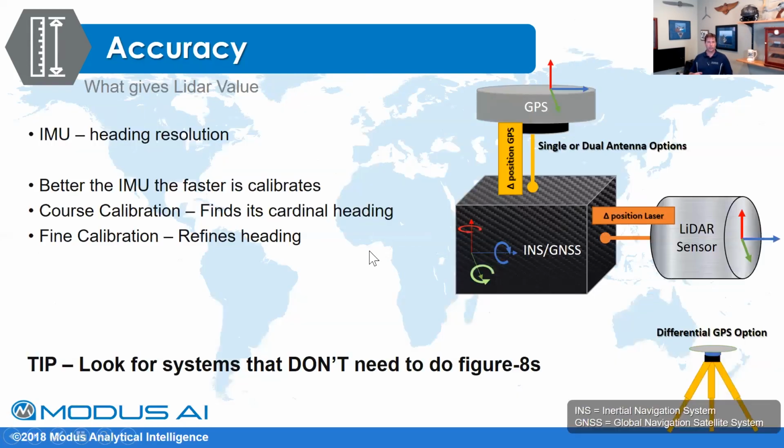All right. So the last little bit with accuracy is getting into the real system now that you know why that's important, and that has to do with the IMU. The GPS part of that is pretty germane. Some systems have dual, which does a little bit of heading correction. SBG Systems has a dual, I think it's the Ellipse 2. But you also have single systems that work just fine. A lot of the reason to have dual is to remove the need for a fiber optic gyro and that additional weight. But it really depends on what kind of equipment you have.